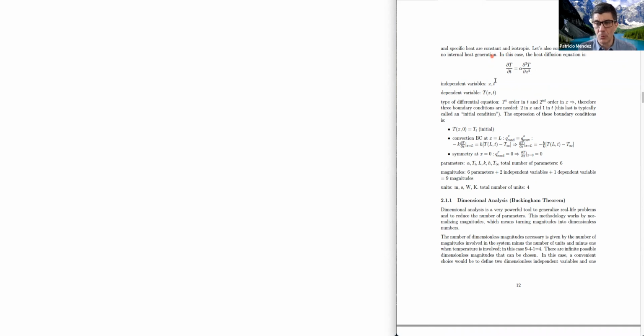And we end up with this equation that isn't innocent looking, but is anything but innocent. This equation is the same equation you write for pretty much everything. It all depends on the boundary conditions and the geometry of the body. So in this equation, we would have two independent variables, space and time, and space is 1D. So we're happy. If it was 3D, it would be X, Y, Z, and T. Those are heavy things. We don't want those right now. One dimension in space, one in time. The dependent variable is only one, that is temperature, that depends on X and time, position and time.